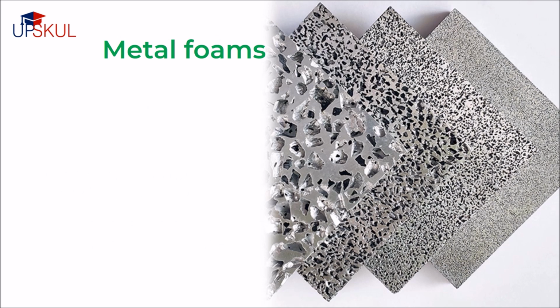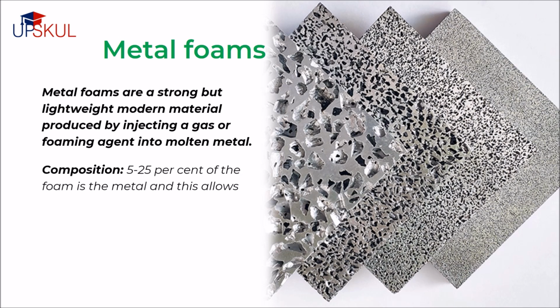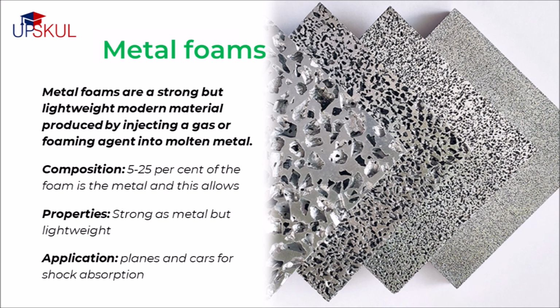Metal foams are a strong but lightweight modern material produced by injecting gas or foaming agent into molten metal. Typically, only 5 to 25% of the foam is metal, and this allows the material to retain much of its strength but without the density or weight of a solid metal. Metal foams are often used in vehicles such as planes and cars, as they absorb shock effectively if the vehicle crashes.